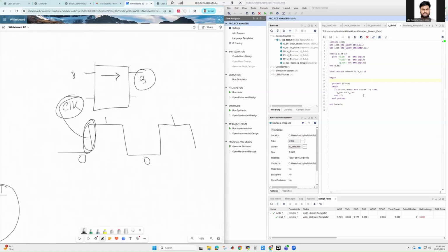So we will use this D flip-flop. As you can see, what I have already told you is written here in code. Clock event is the transition, and clock equal to 1 represents the positive edge. When there is a change in the clock, it can be 0 to 1 or 1 to 0. Then clock event generates a high signal, and we are making sure that we are taking the positive edge. That's why we are also adding the condition of clock equal to 1. Okay, so that ensures that we are taking this edge, and as you can see, Q out is the output of this D flip-flop, and D in is the input. So whenever there is an edge in the clock, it just transfers its input D in value to its output Q out. Okay, that is a D flip-flop, actually.